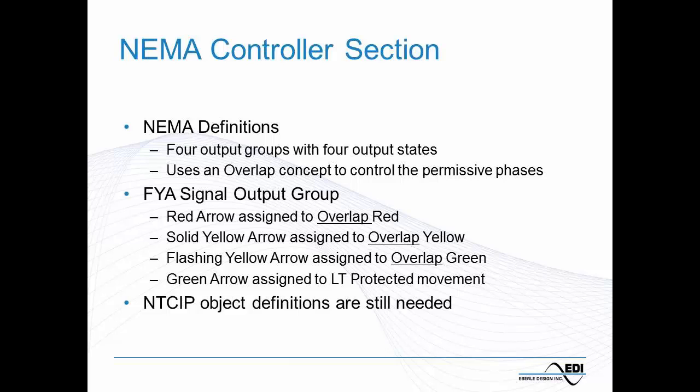The MMU is a little different. In an MMU, we're more hardware centric. We're dealing with load switches that have 3 outputs, MMU channel inputs that have 3 inputs. Everything has historically been done as a 3-input group, red, yellow, and green. Now we have a 4-section movement to monitor. So we're going to see that creates some interesting challenges with the hardware.